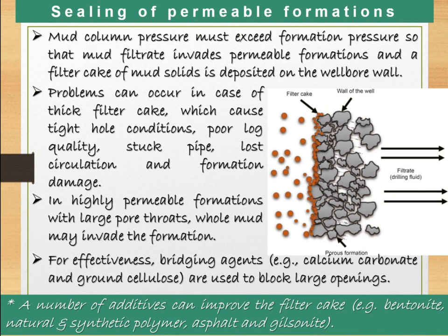Whole mud may invade the formations, because whenever permeability is very high, that time these kinds of things are required. And by chance, if we are making this out of control, mixing more and more, what will happen? Cake density will be more, the cake thickness will become more, and it will stick the pipe again. So again, balance must be maintained. Okay.